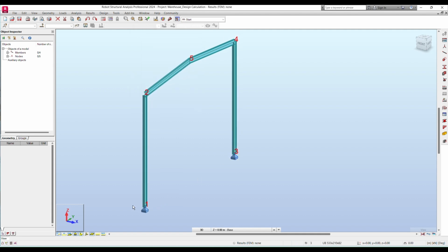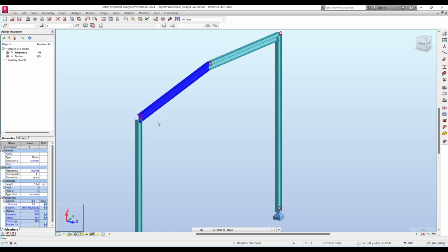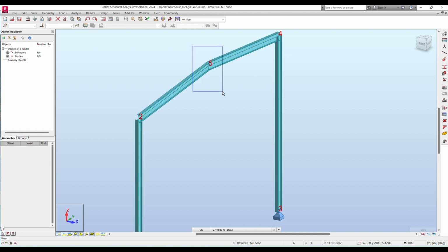Now, as the width is 18 meters and the total span is 30 meters, we need to split it into 5 meter intervals. But as it has a larger width of 18 meters, there is a possibility of maximum movement occurring at this fixed point, at two points: the end of the rafter and the middle of the rafter. So we need to develop haunches here.